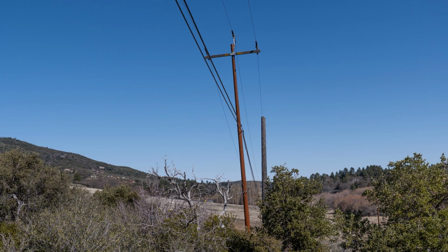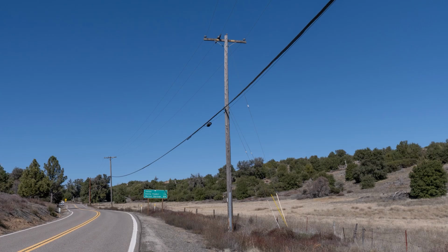Steel poles don't bend and deflect the same way wood poles do. However, when unchecked horizontal loads are applied to steel poles, over time they can start to lean into the load as the soil foundation gives way. Because of the tendency of overhead poles to either deflect or lean, almost all horizontal loads caused by the conductors need to be counteracted with a guy and an anchor.